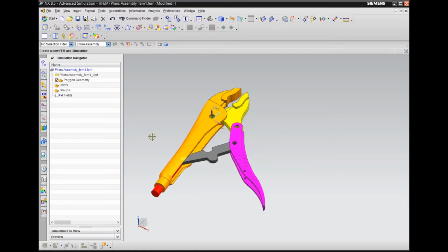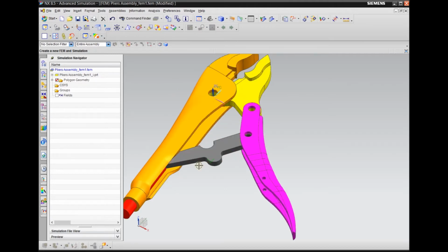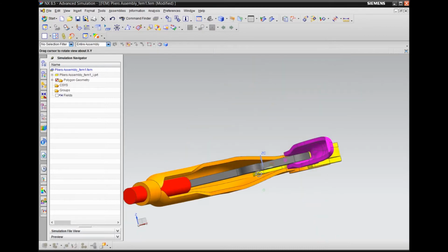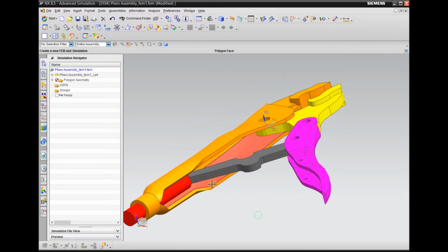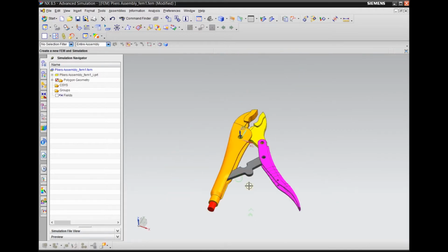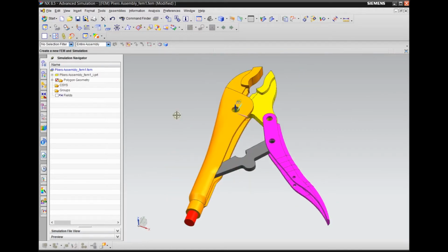So first, to create those 2D meshes on this kind of part, that's sheet metal, we want to find the middle surface of this piece. So what do we do? How do we find the middle surface? We're going to modify this file. It's called the idealized part. The idealized part is idealized from your CAD model, from your PRT file.